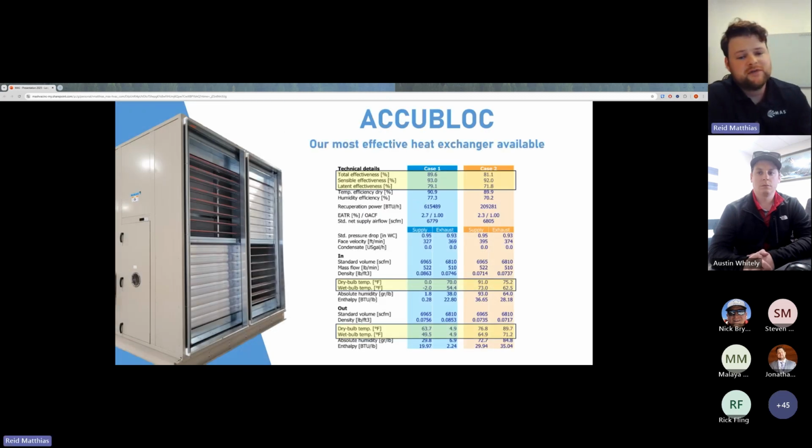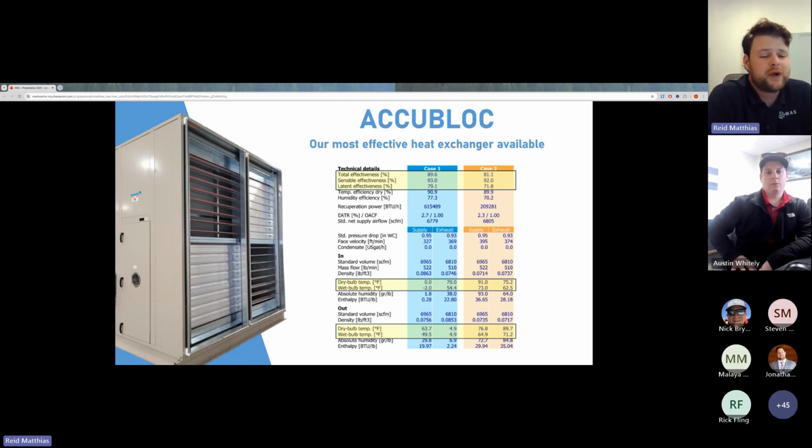The next energy recovery device I'll touch on is AccuBlock. I could do an entire webinar just on AccuBlock because it's such a powerful energy recovery device. The short of it is, it's incredibly effective. You're seeing here close to 90% total effectiveness during the winter.